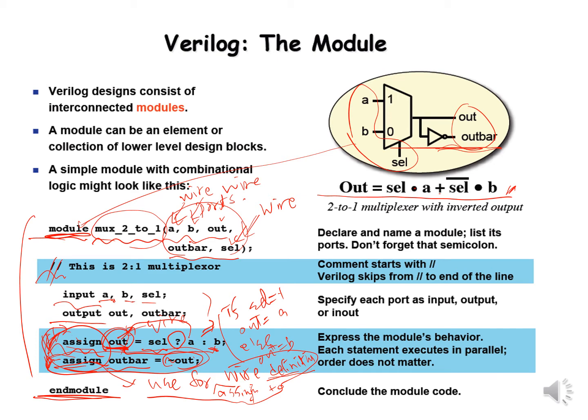There's no difference whether you move this assign statement to the top. There's no distinction in the assignment statement order. All the statements are executed in parallel, concurrently. This is how the actual hardware works. This is different from the conventional programming language.